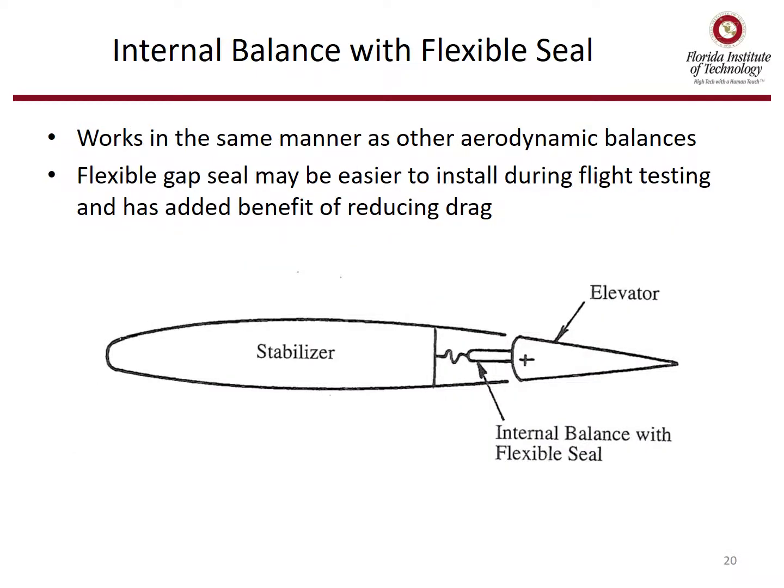The internal balance with flexible seal works in the same manner as other aerodynamic balances. The flexible gap seal may be easier to install during flight testing and has the added benefit of reducing drag.